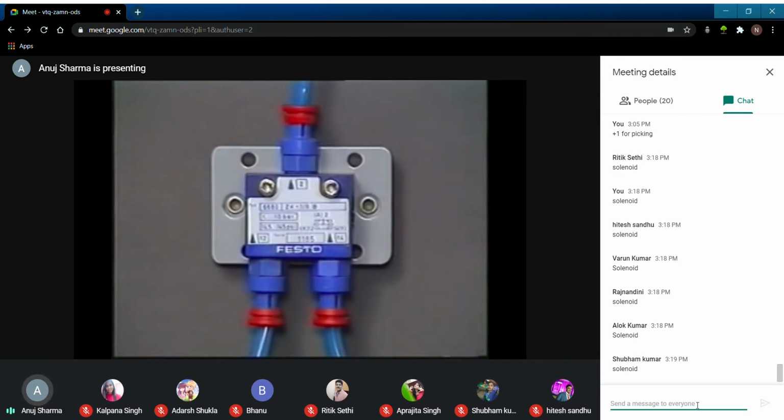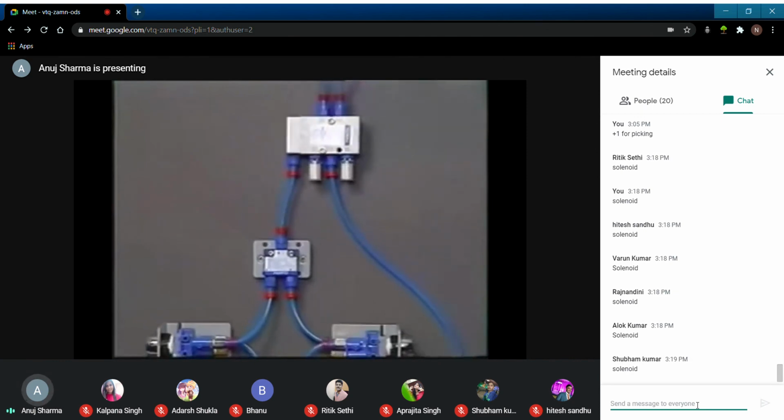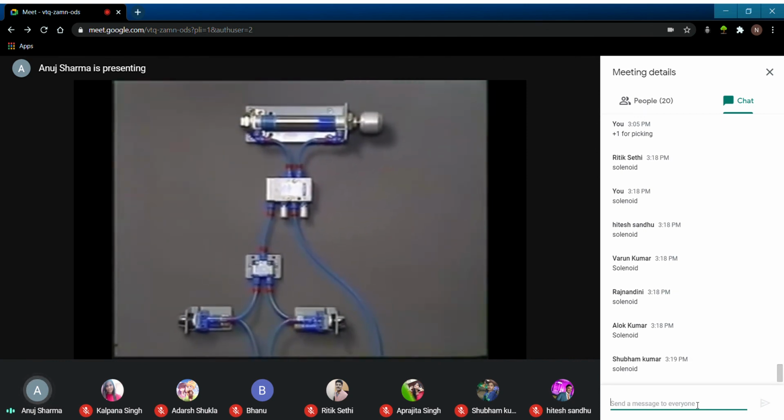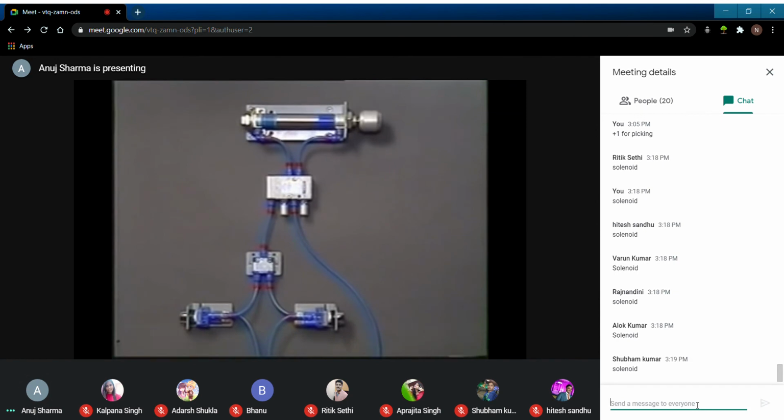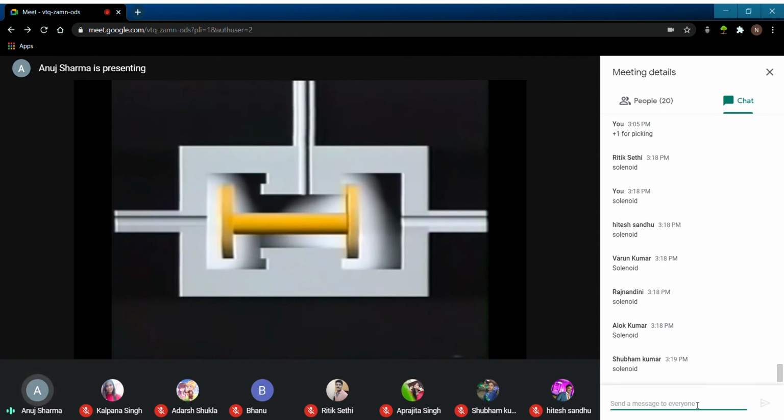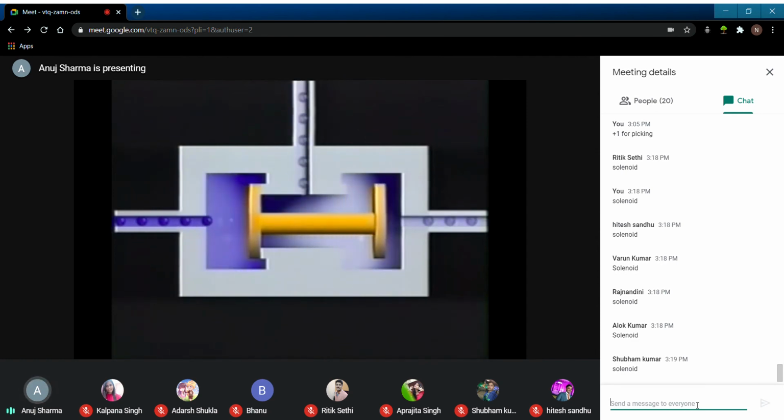The AND valve enables the logical AND decision to be made pneumatically. Therefore, the piston extends only when both push buttons are pressed simultaneously. AND valves are also called two-pressure valves. This shows how the two-pressure valve operates. When air enters the valve from one side, the output is blocked. If this signal is lost and air enters the valve from the opposite side, the output is also blocked. Only when two signals enter the valve is an output signal produced.